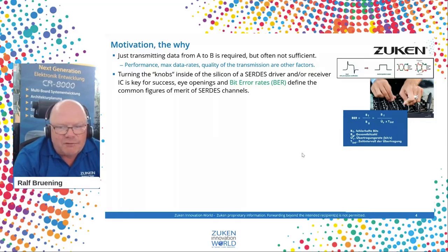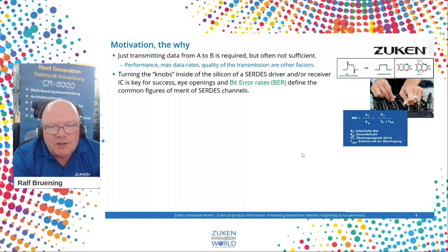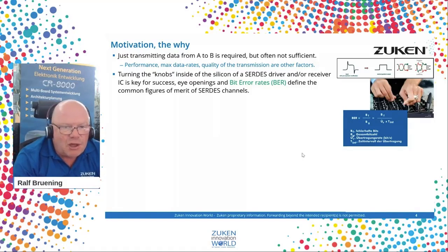The fancy thing of SerDes chips is that you can tune them, meaning by setting information into a register, you can define or change its performance. You can change the output voltage swing, you can change the energy which the buffer is feeding into the channel.